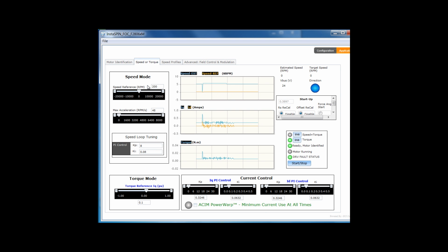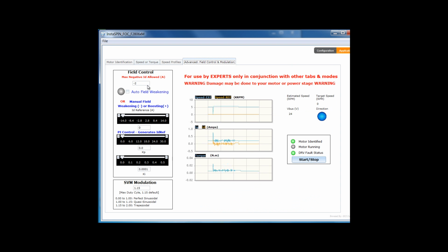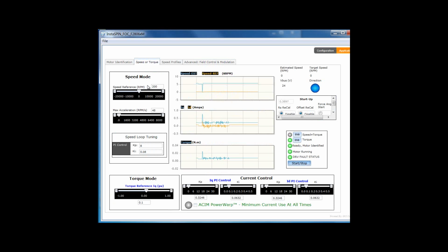And now we can try moving all the way up into the trapezoidal. Coming back, so we had 5,200, 5,600, and now we're at 6,400. So from the sine wave up to the full trapezoidal, we've gained over 1,000 RPM, so over 20%, which makes sense based on the relationship between the sine wave and the full trapezoidal wave.